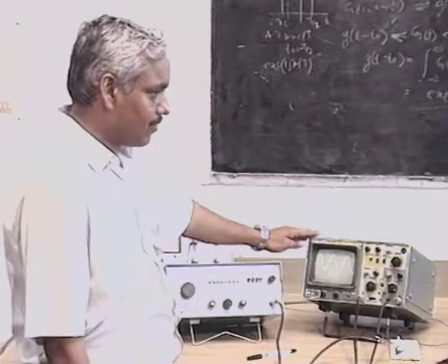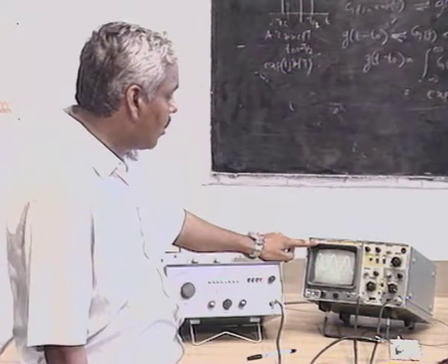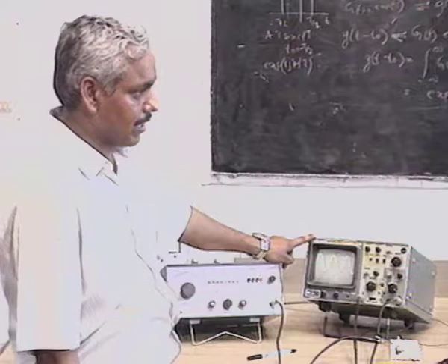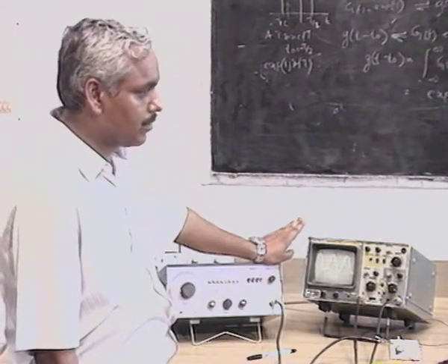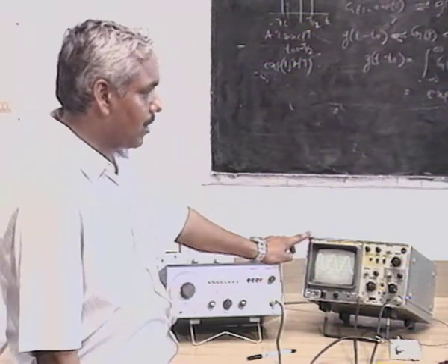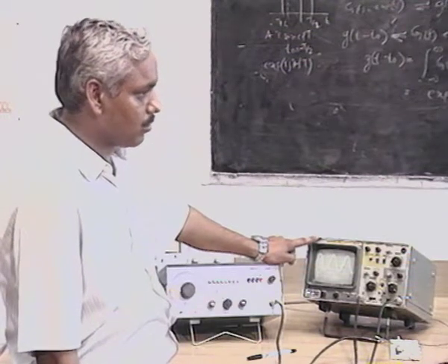So what do you mean by RMS voltage? In this varying signal, the voltage is varying with respect to time. So RMS value is the root mean square value of the signal. So in this case, if you know the maximum value of the voltage, that is Vm, the peak voltage, then you can find out the RMS value by multiplying Vm by a factor of 1 by root 2.